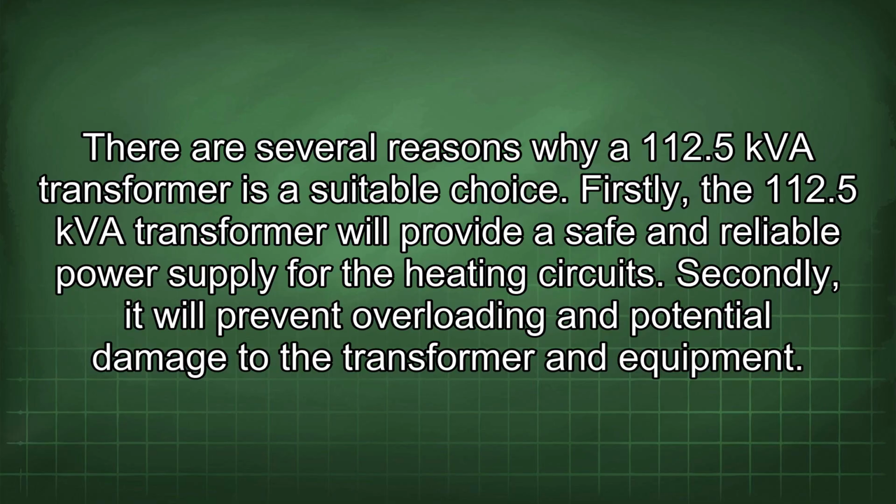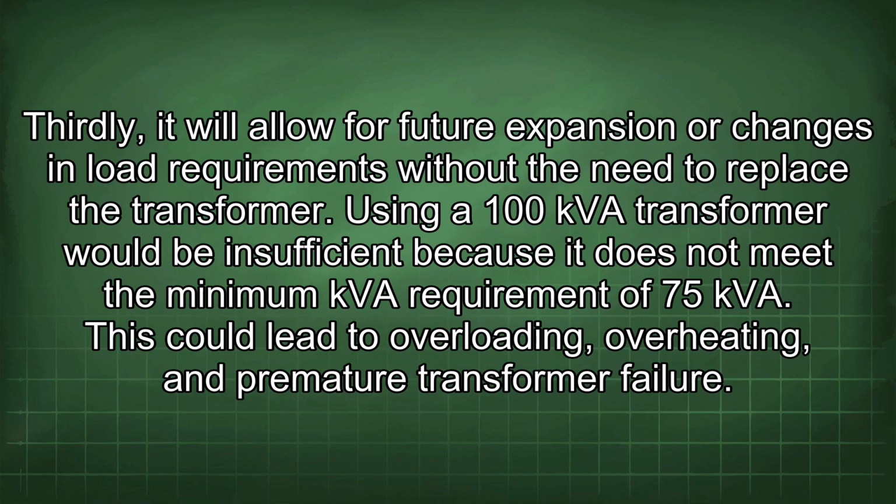Firstly, the 112.5 kVA transformer will provide a safe and reliable power supply for the heating circuits. Secondly, it will prevent overloading and potential damage to the transformer and equipment. Thirdly, it will allow for future expansion or changes in load requirements without the need to replace the transformer. Using a 100 kVA transformer would be insufficient because it does not meet the minimum kVA requirement of 75 kVA. This could lead to overloading, overheating, and premature transformer failure.